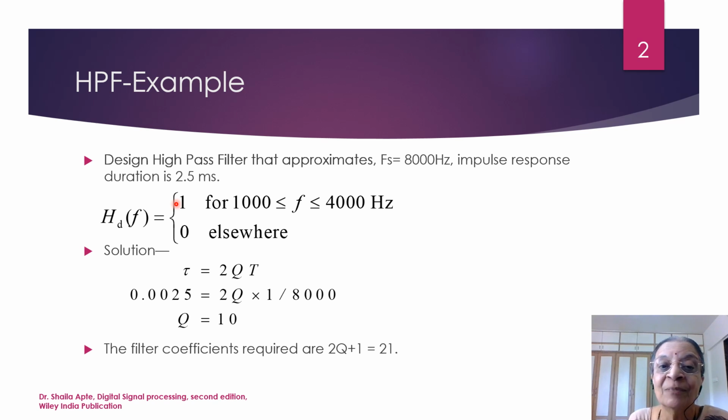So we are trying to represent the frequency response of the filter as a replicated spectrum, and for that replicated spectrum we write down the Fourier series in time domain. Because it is an infinite series, we truncate it, and then we shift it because it is non-causal, so we have to make it causal also. Then we design the filter.